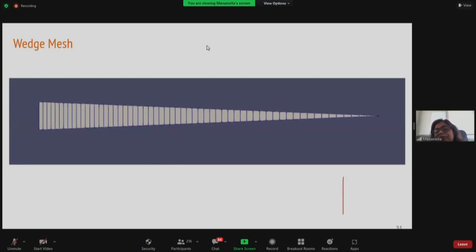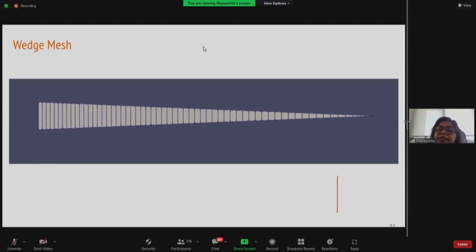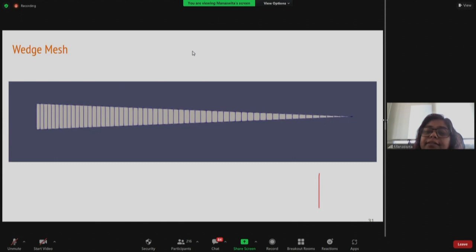See, typically in general, when we simulate something, we simulate a practical problem, right? And in any experiment you can think of, we know the flow rate. That's why we define the flow rate at the inlet, either the mass flow rate or the uniform average velocity.